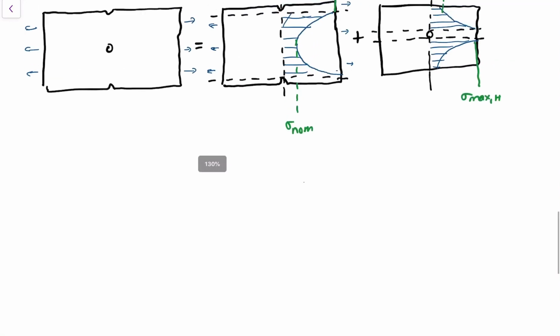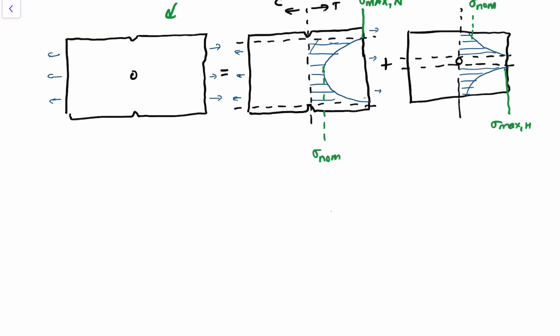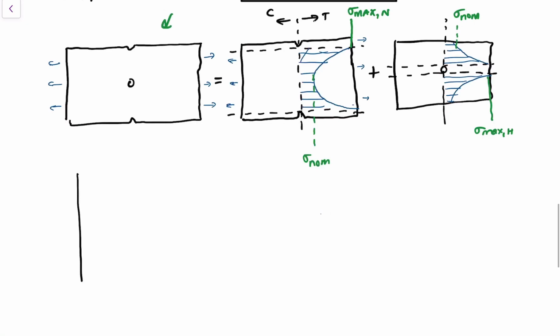So what would the stress distribution look like in this case? So if we assume that they're far enough, so for that I'll have to draw an unrealistic diagram. And again, we won't trick you or give you any additional plots. Just make yourself familiar with any of the plots you already have in the textbook, and that should be enough. And if we do give you something like this, where both the features are in the same line, then you can make the assumption that they're far enough that their stress distributions don't overlap or they don't affect each other such that the stress concentration factor increases more than what you've pulled out of the plots.